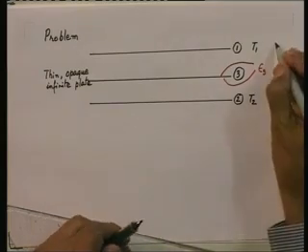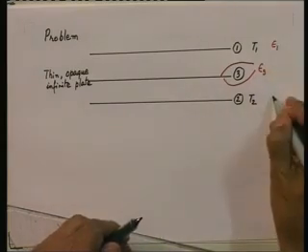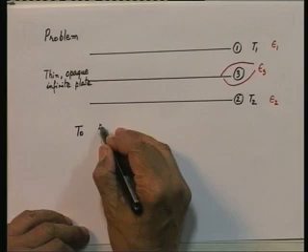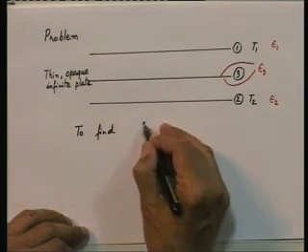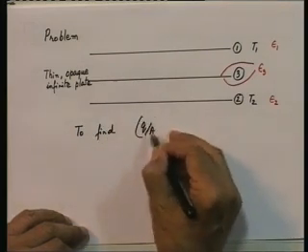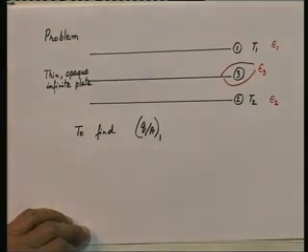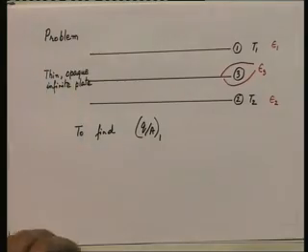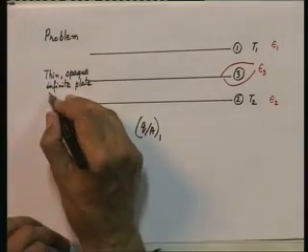Surface 1 and 2 are diffuse gray of course. So, their emissivities are epsilon 1 and epsilon 2. So, in between you insert a thin opaque infinite plate which is also diffuse gray and has an emissivity epsilon 3. Now, what is to find? q by A 1? That is the problem. This thin opaque infinite plate incidentally is often referred to as a shield.